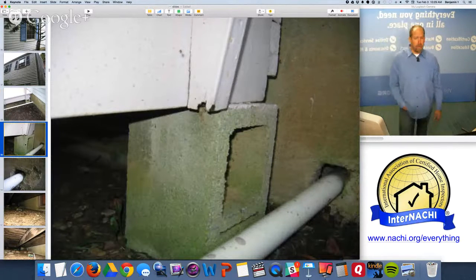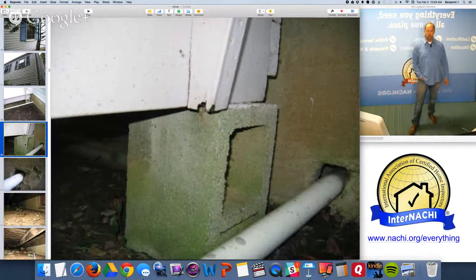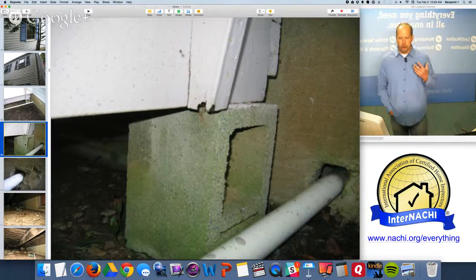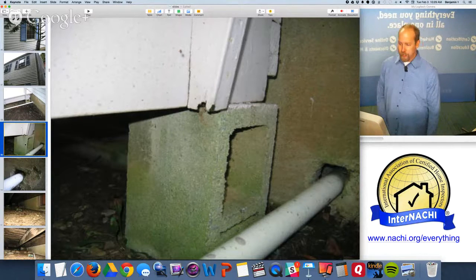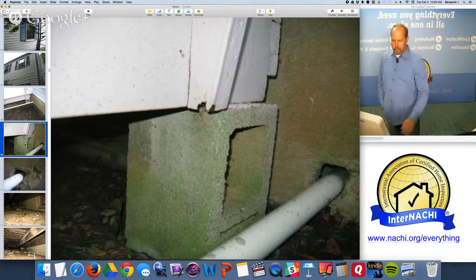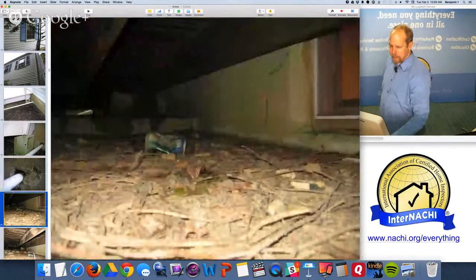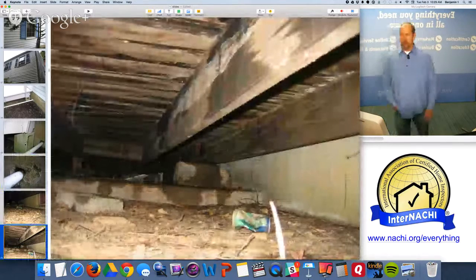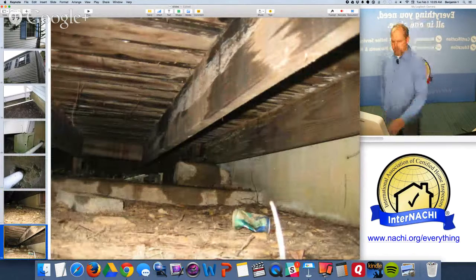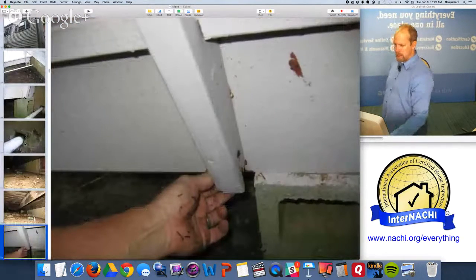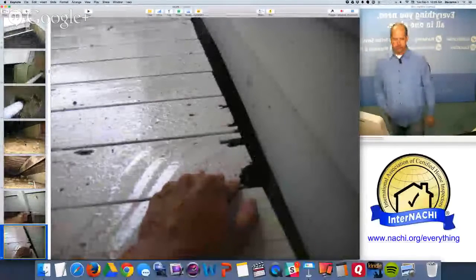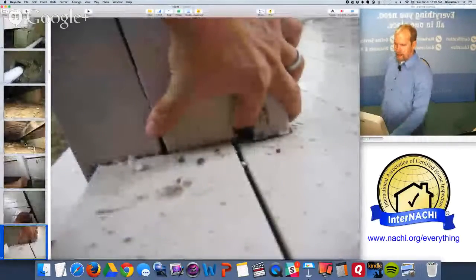And the rear deck porch wooden structure is poorly installed. The footings, the foundations are simply blocks laid on their side, and they built it on top of that. The floor joists are about 20 feet long, 2x10s, 2x8s. So the deck actually bounces. There's a lot of wood rot, structural problems. The floorboards on the ends are rotten. So I'm taking a look.